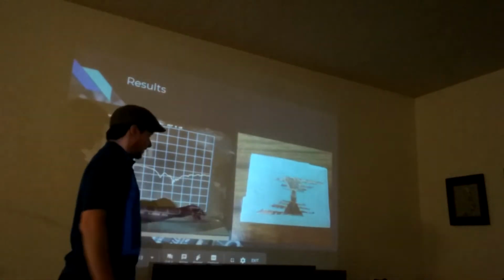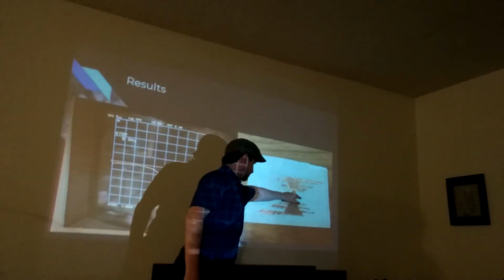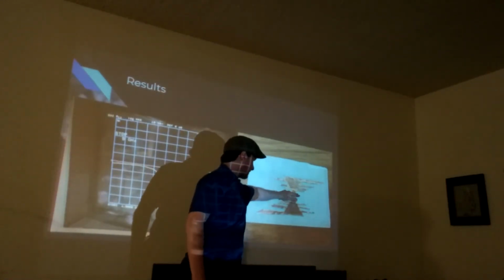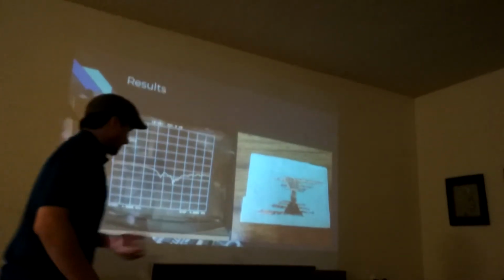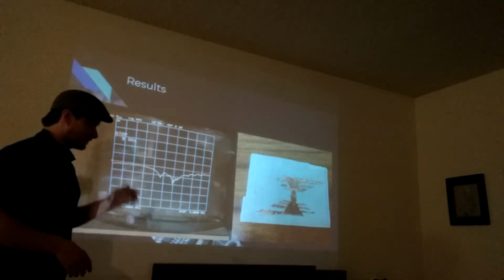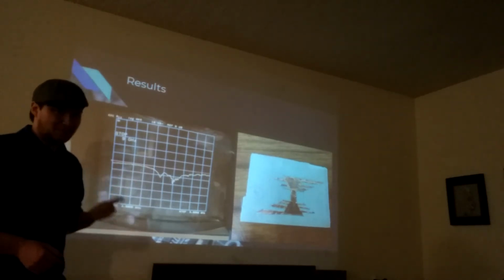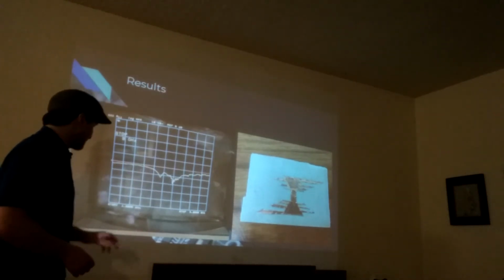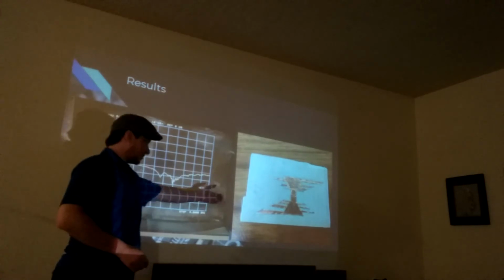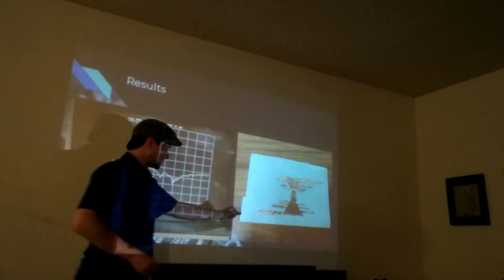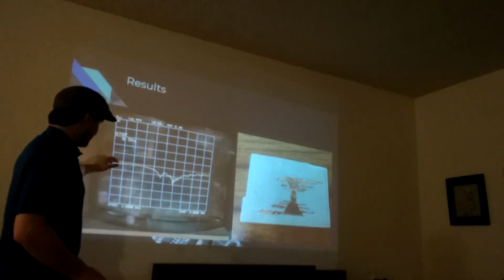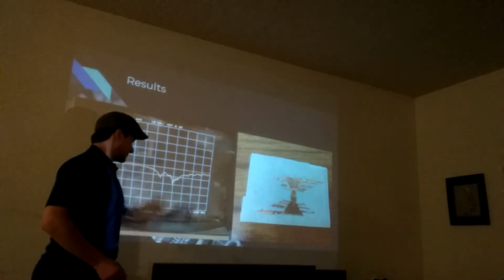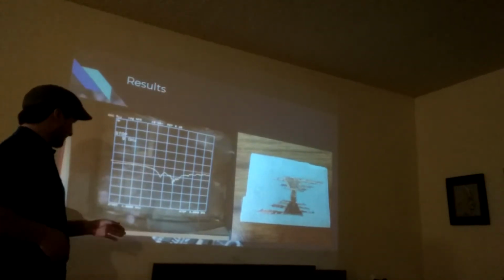So, my original test, I didn't make an incision here and cut between the negative side and the positive side. This was because I wasn't sure if this type of antenna operated more like a patch antenna or more like a dipole antenna. So I tested this with the ground plane behind it first and the probe feed sticking through right here, and found this as my reflection coefficient, or S11 pattern, across several frequencies.